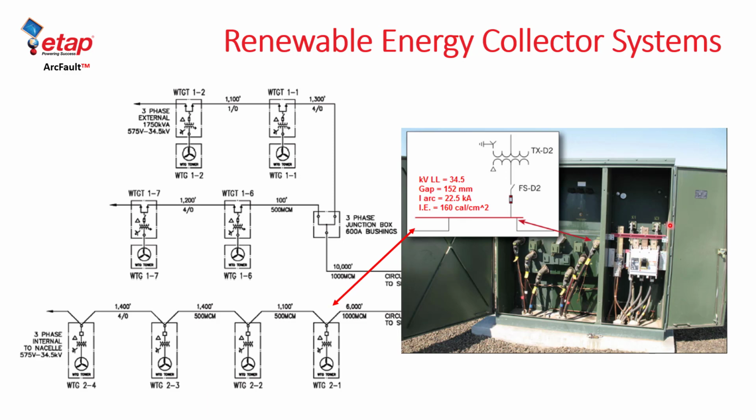Of course, for the low voltage part of the system, we have classically used the IEEE 1584 model. That model has been used by the industry successfully for the arc flash calculations in this area for many decades. The problem is that models were not really available for longer gap arc flash events in the medium voltage collector side of the circuit.